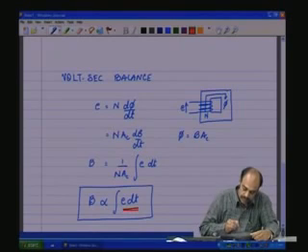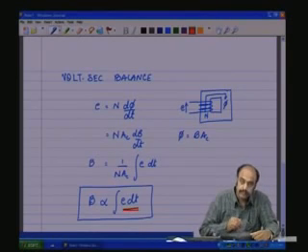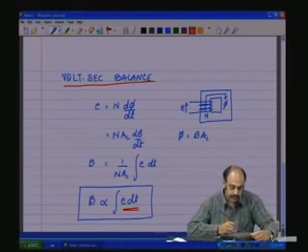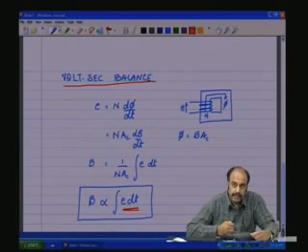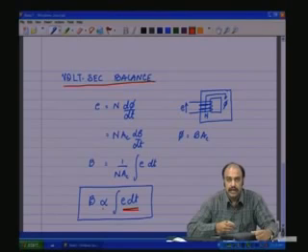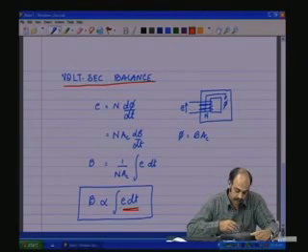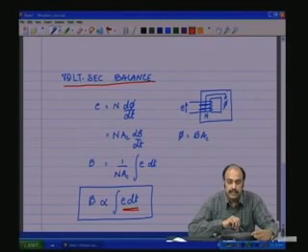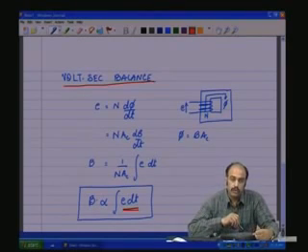This is the volts and this is the second. That is what is known as the volt second balance, meaning this integrand on integration should not have a waveform that is continually increasing, meaning E should not be a DC value. If E is a DC constant value, on integrating, this would be the constant into T. So, it is a continuously increasing value, and after some time the flux density for the particular core,